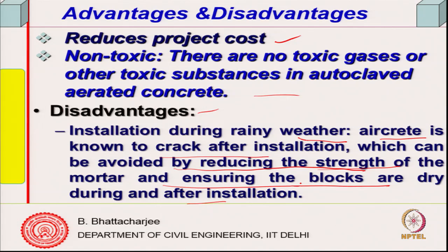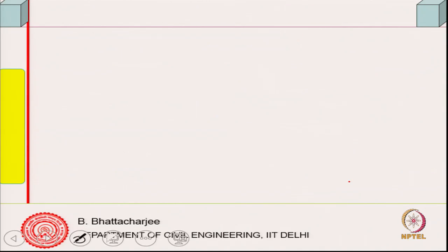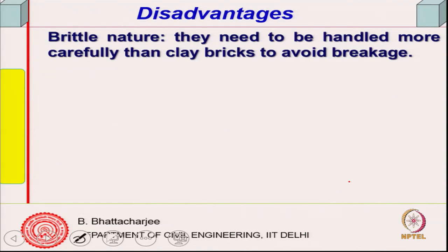In fact, weak mortar is what people generally look into, because Poisson's ratio, elastic modulus, etc., are all empirically related to strength as we measure. And also blocks should be dry during and after installation. The nature is obviously brittle, this should be there.